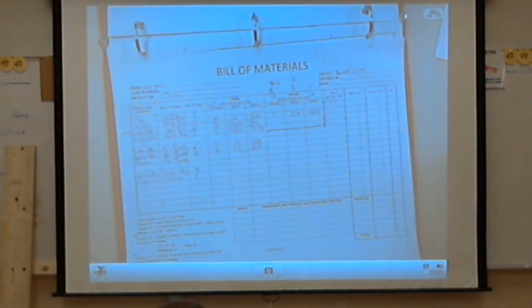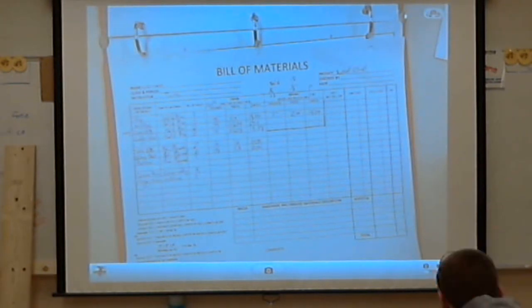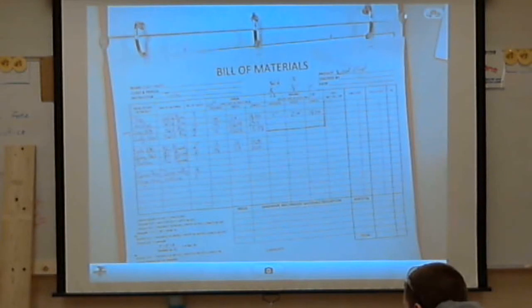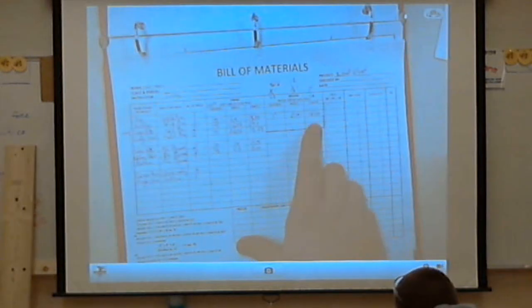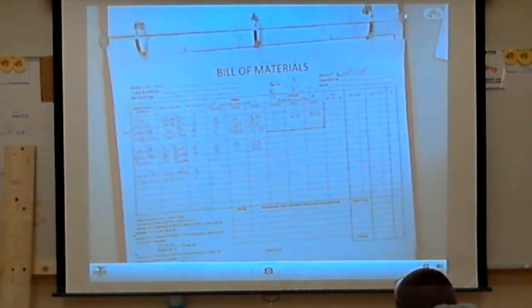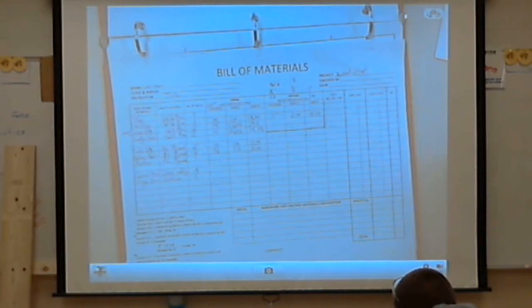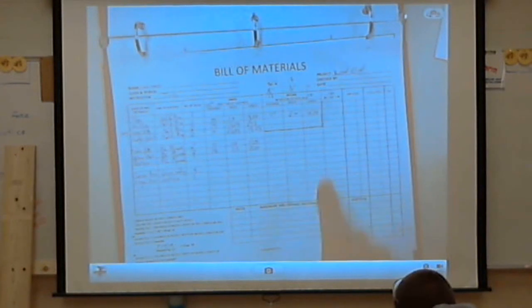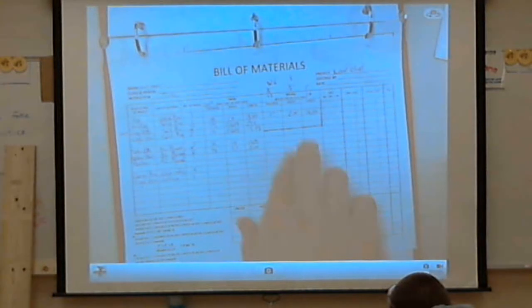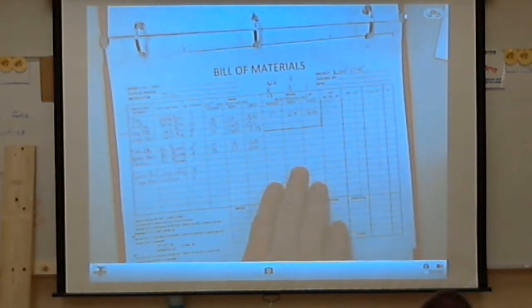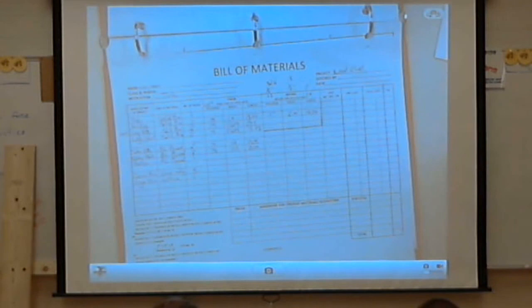Now solid lumber is different from plywood or trim, so it's sold in different units. The reason is because of what dimensions you manipulate. With solid lumber, you deal with all of the dimensions: thickness, width, and length. With plywood, you only deal with width and length. With trim, you only deal with length. So it's calculated differently, because you only deal with certain dimensions.